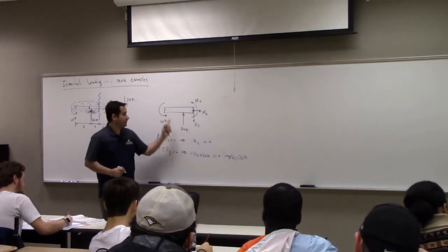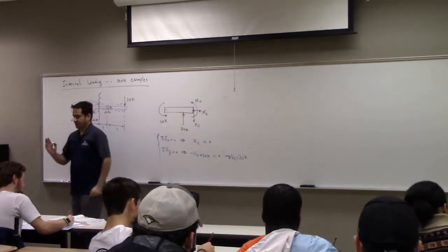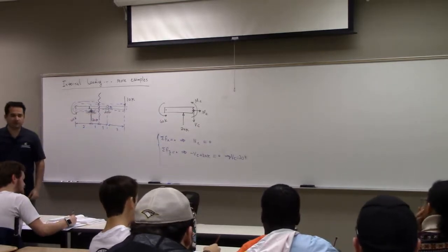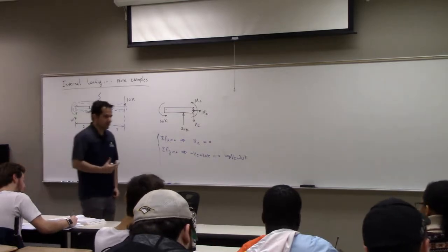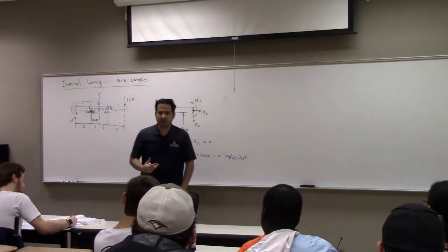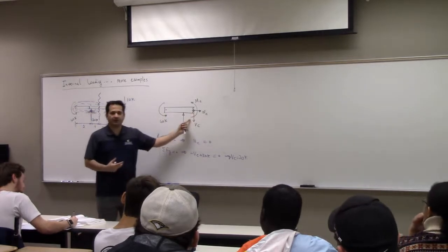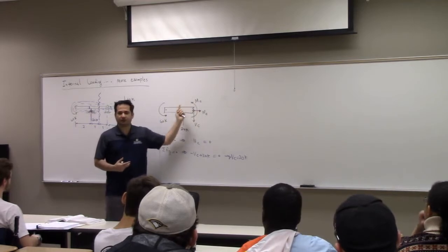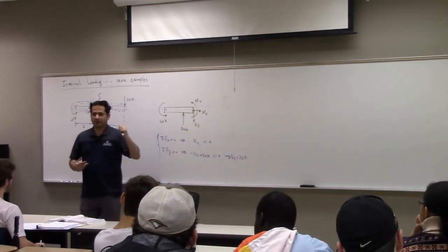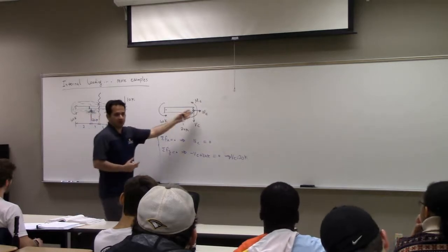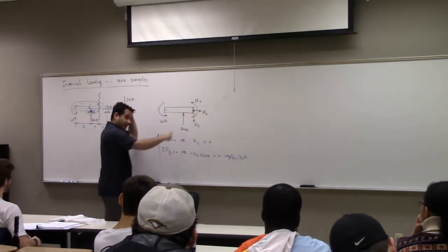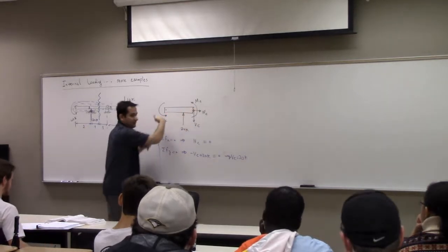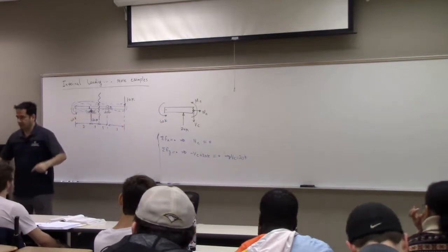You remember this load that goes in the Y direction, they call it shear because it causes a shear. It all comes from the familiar word with mechanical engineering word. People who do physics, they don't care if you have shear or axial or bending. They just call it force and moment. But we, as mechanical or civil engineers, we call this shear load, right? Now, this guy, they call it moment. We call it bending moment. Why? Because this bending moment can cause this structure to bend, right?